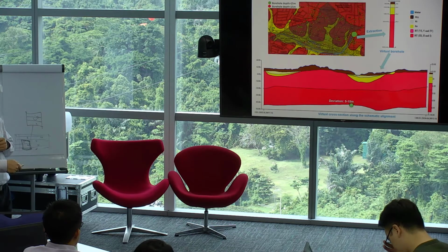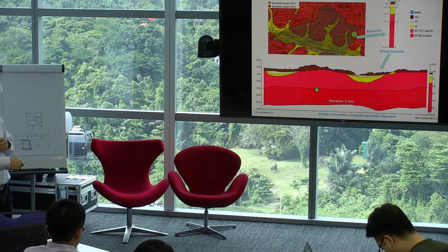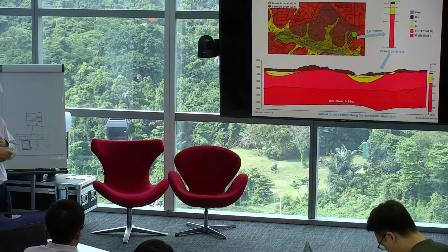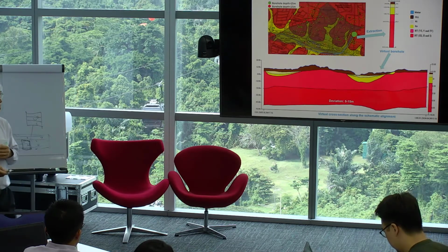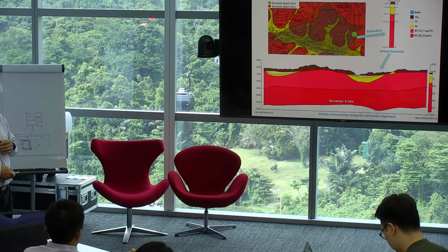So basically, the accuracy is somewhere between 5 to 10 meters. In other words, in terms of the rock head or the soil-rock interface, this line can have an error of somewhere between 5 to 15 meters. So this may not be good enough for a tunneling construction company.